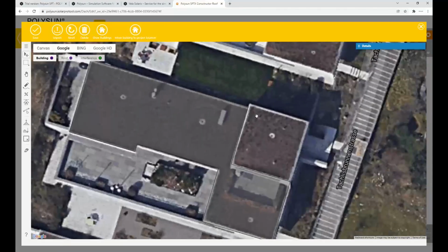And now you can see the existing building, it's already slightly gray here. And now we can use that as a reference. You can see it snaps automatically into the corners here when I select the guiding line tool. And I will just connect these two edges, and now we can align the new building along the old one.